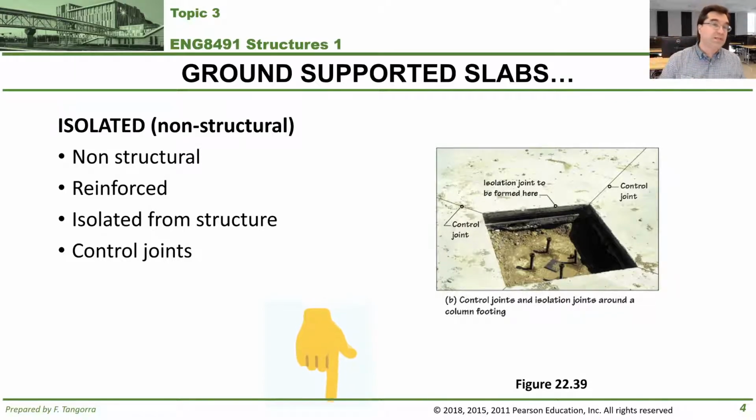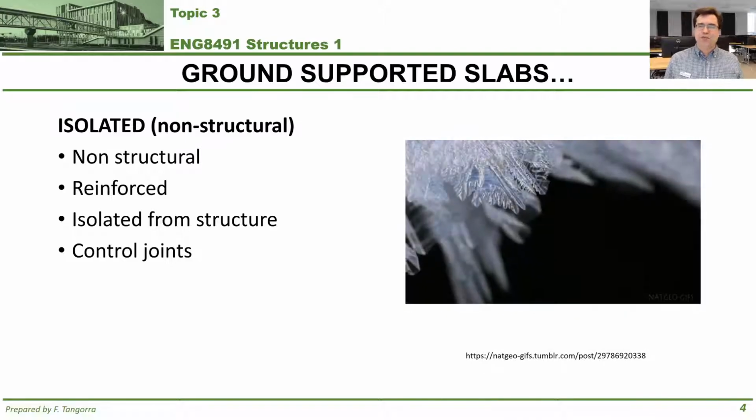Well, this doesn't quite apply to Canadian construction, and that's because in Canadian construction, you have to build typically the structural portion of a building below a slab, even if that slab is on ground level. And that's because in Canada, you have to deal with frost, right? You have low temperatures, and you have to put the structural portion of something below the frost line, unless you do some other stuff.